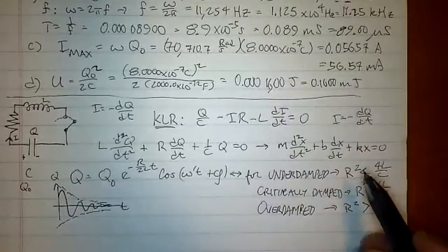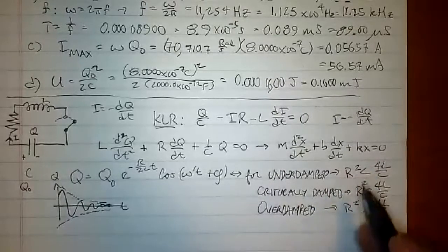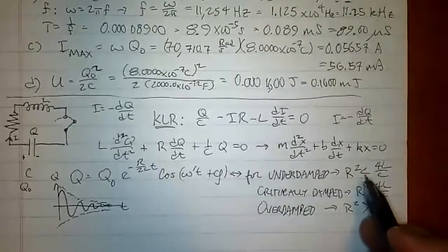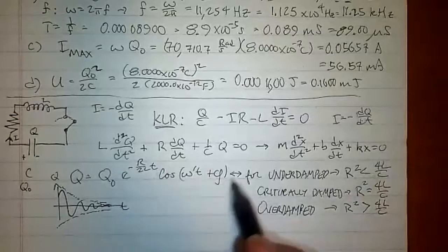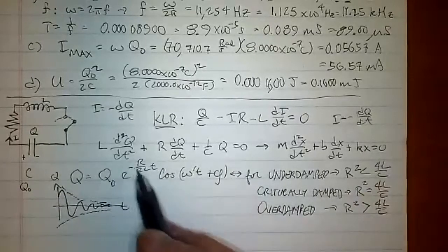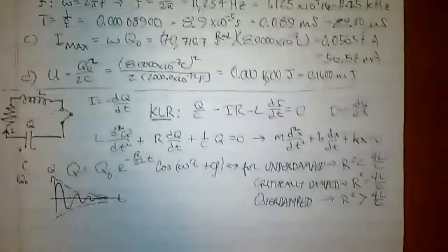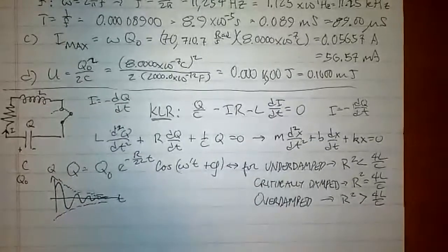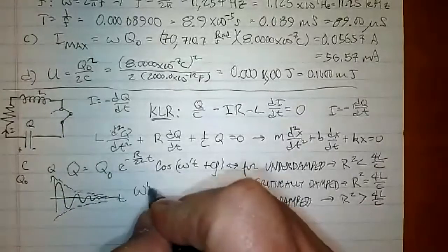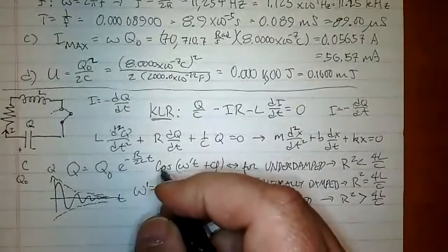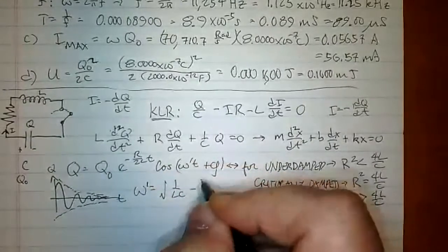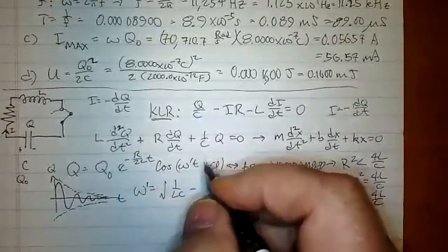Remember in the quadratic formula, b squared minus 4ac. If that's negative, then you're going to get an i. When you get an i, you get an exponential that oscillates, but the real part will actually come out here and be multiplied, so that's why we're getting the damping. Okay. Now, I should also point out that this omega prime is in fact equal to the square root of 1 over LC minus R squared over 4L.